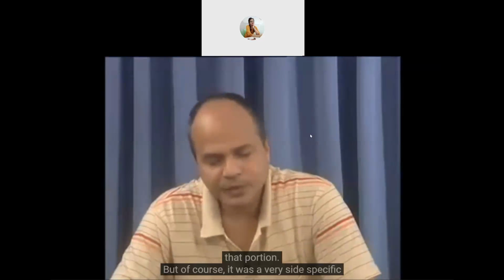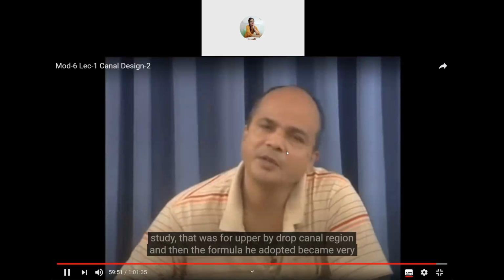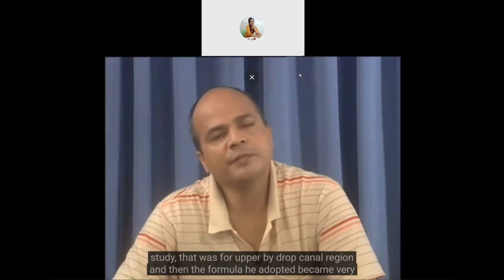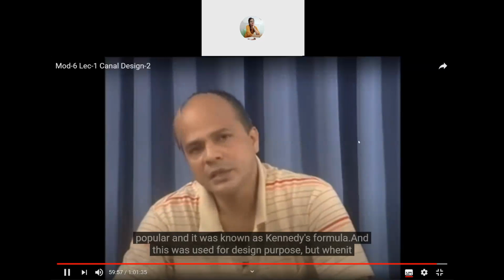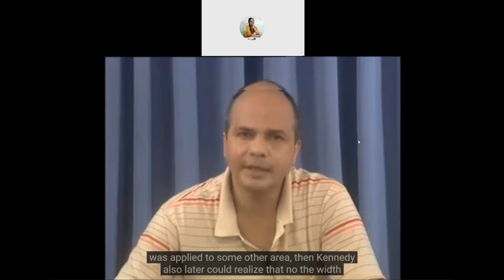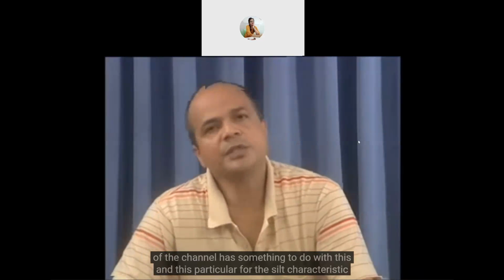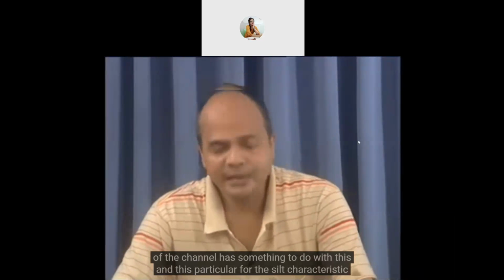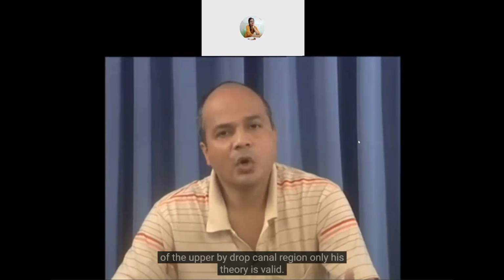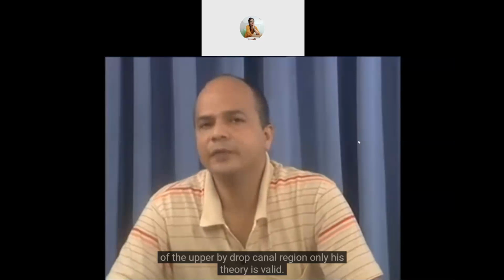But of course, it was a very site-specific study. It was for the Upper Bari Doab Canal region, and the formula he adopted became very popular, known as Kennedy's formula, and it was used for design purposes. But when it was applied to some other area, Kennedy also later realized that the width of the channel has something to do with this, and that only for the silt characteristic of the Upper Bari Doab Canal region is his theory valid.